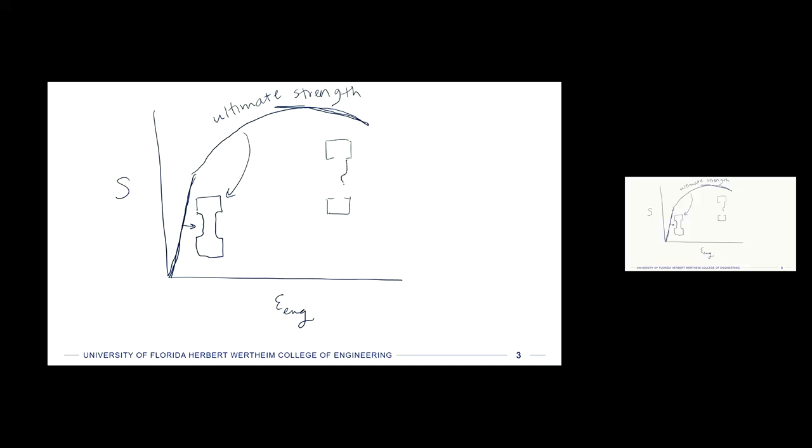But then we're going to start to get some sort of necking in the middle, right? And I drew it kind of crazy, but it starts to get a real thin section because we can't really change the volume of this thing too much. So eventually it's going to break. And then as it comes down to maybe a fracture or a complete yield point there, the necking will continue until the section is so thin that it can no longer sustain the load that's on it, and the specimen will fracture. So this is just kind of a qualitative chart of what happens during plasticity.